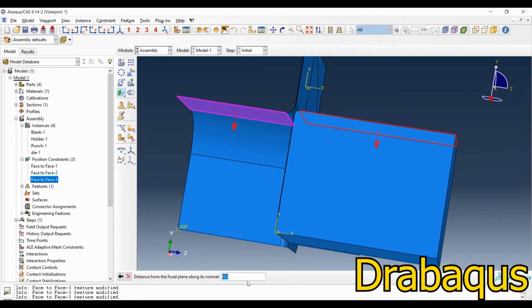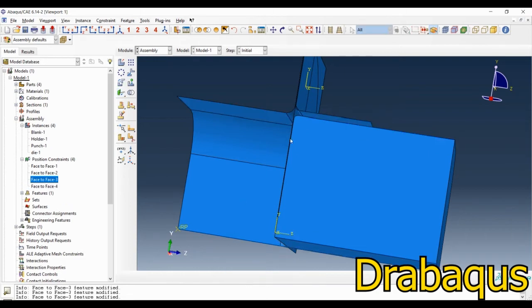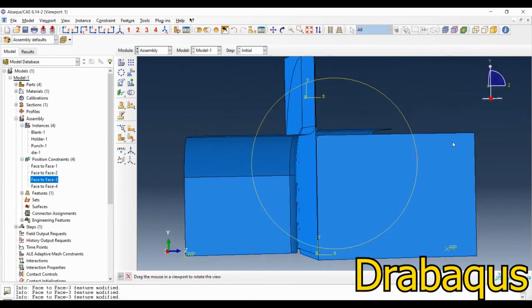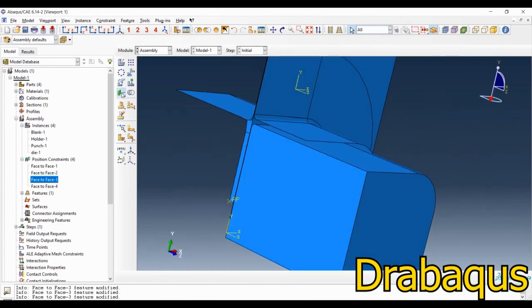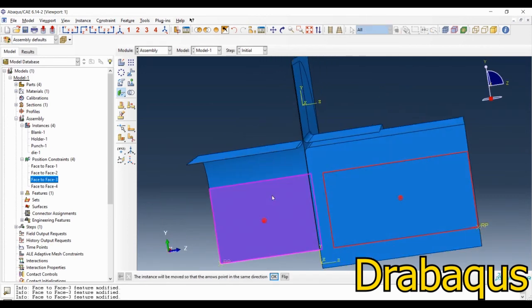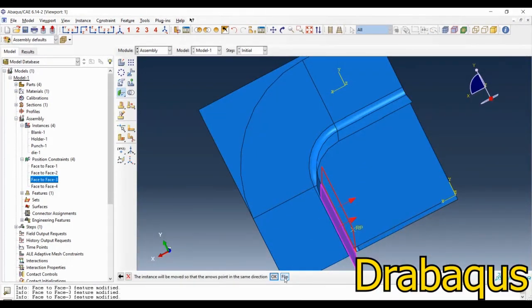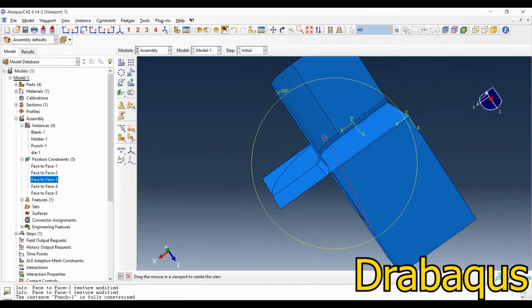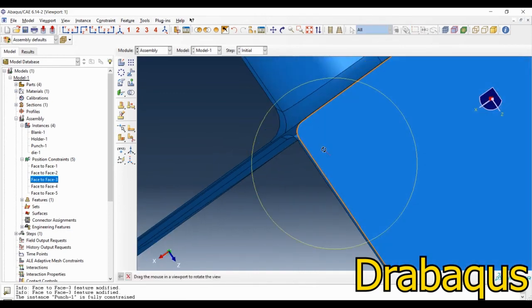And here the clearance must be equal to 1 millimeter and 1.05 millimeters from both of the walls. This is from the top wall, and this one is from the side walls of the die. Assigning the arrows, and again 1.07. This is the clearance of my mold.